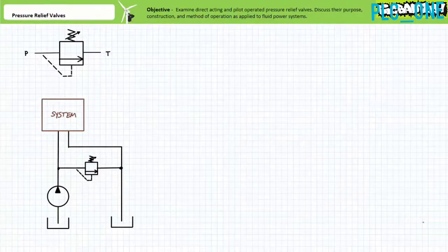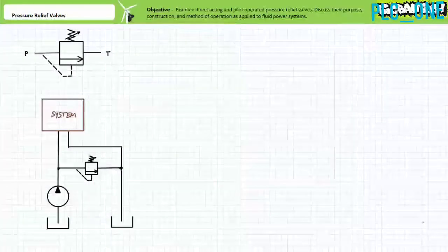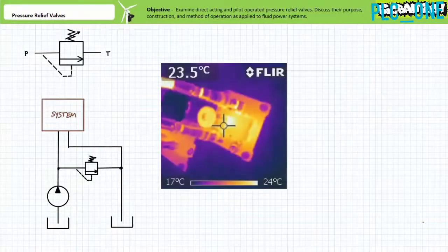This is to suggest that a properly designed system only infrequently goes to the trouble of building pressure to a certain level and then just dumping it to tank without accomplishing any work. The pressure relief valve in the act of relieving pressure is essentially wasting energy. Pressurized flow is converted to noise and a whole lot of heat, contributing to inefficiencies of the larger system.